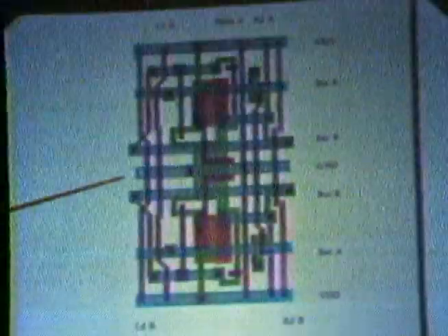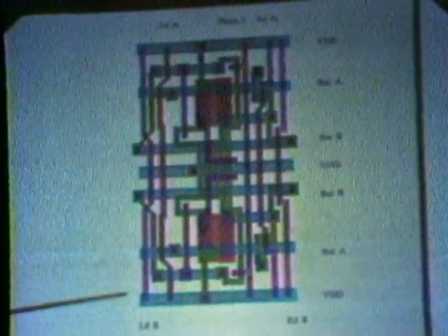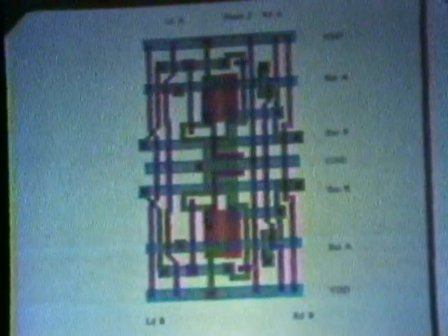Actually, this is a layout picture of 2 cells of the OM2 RAM cell. Again, the array concept that they use here is with horizontal metal lines for power and ground, alternate cells mirrored so that they can share the ground line between them, and then the next one shares the VDD line.